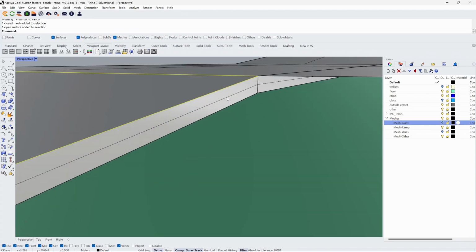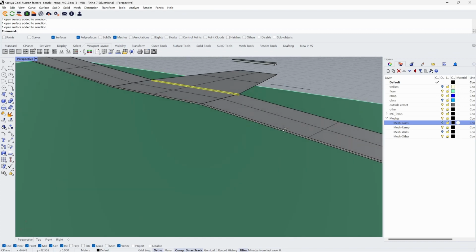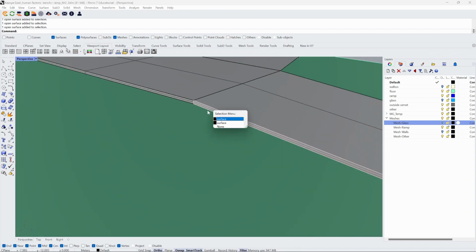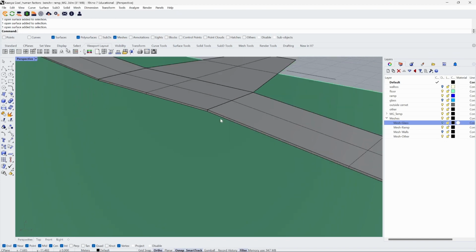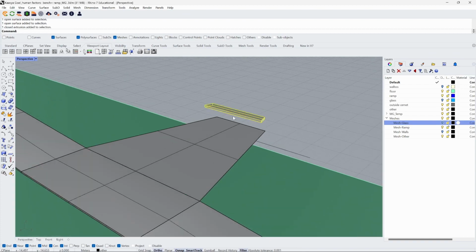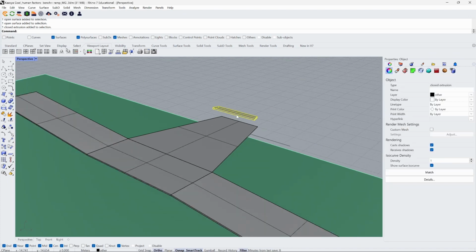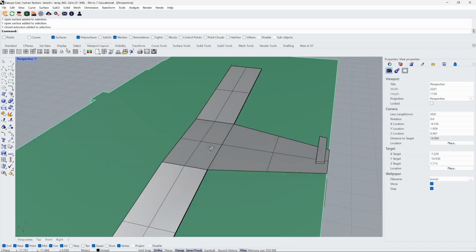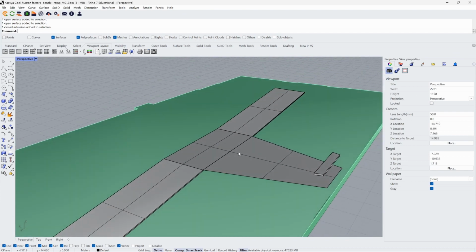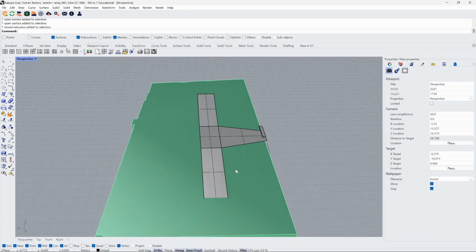So it just looks like a solid geometry, but actually isn't. So we have lots of individual surfaces here. That is not ideal because that will create very, very many meshes versus, for instance, this object here, which is a closed extrusion, will be only one mesh. So here we would want to fix this model a little bit by, I think,